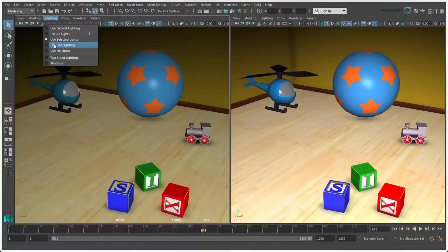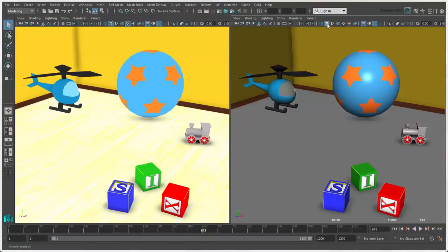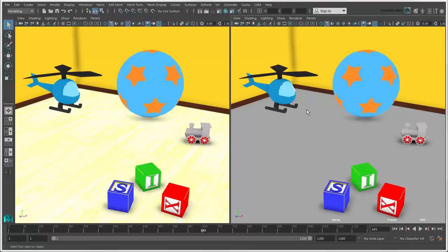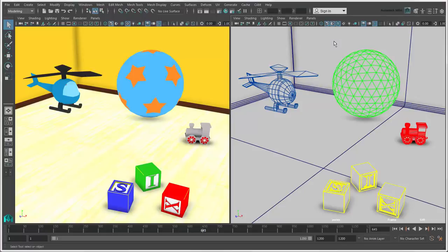The Flat Lighting option uses an ambient light that looks like this if textures are on. If shading is on, the effect is like a constant shader, which is sometimes useful if Wireframe on Shaded is also on. If you don't want to see the object material's color, just select the default material option.